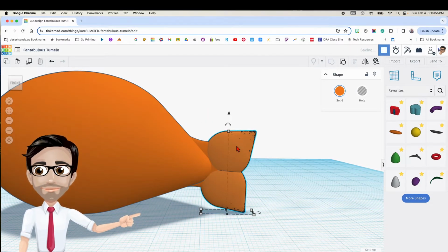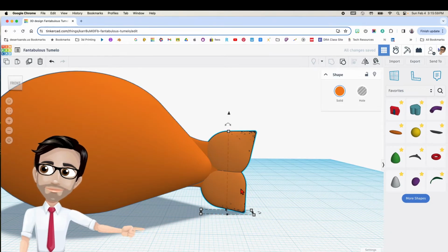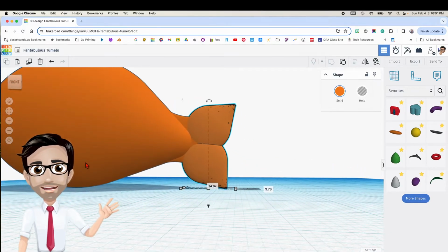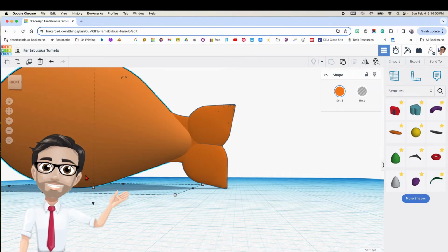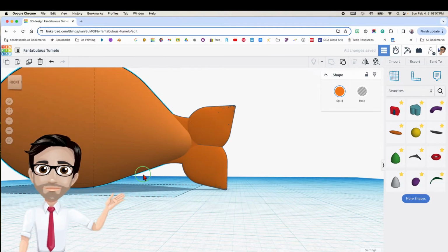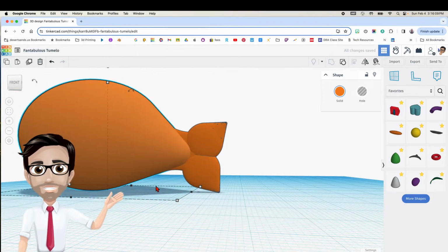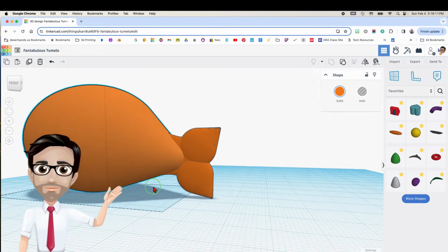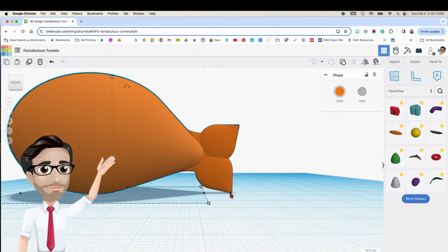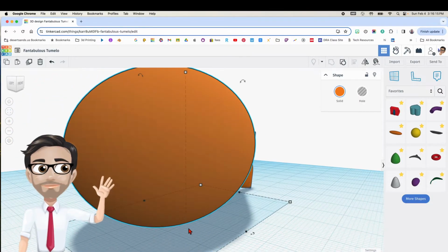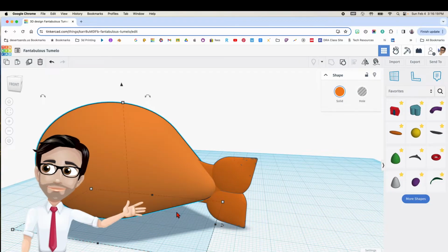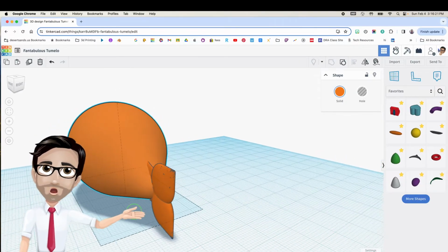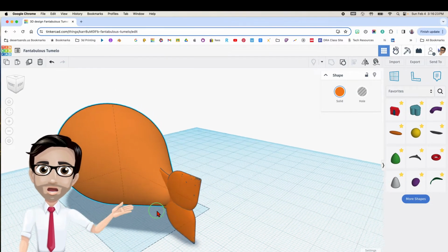And what about D? It's very important that this tail be touching the ground. I didn't even check if it's touching the ground. Let me see, Control, or just the letter D. Oh, okay, it wasn't. There. Very important that these things be touching the ground, because when you print this, the tail, the body, and the fins on either side are going to make it stand on its own, or lay on its own, without tilting over left or right.